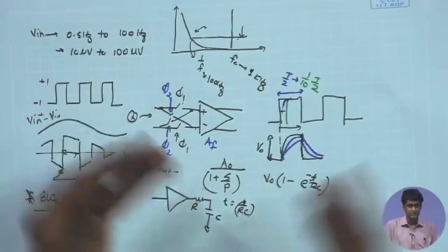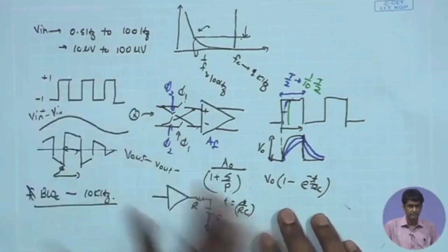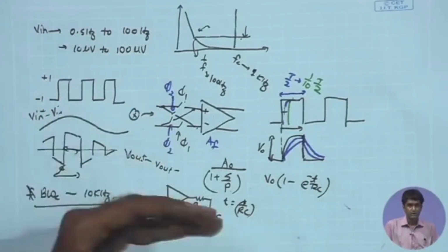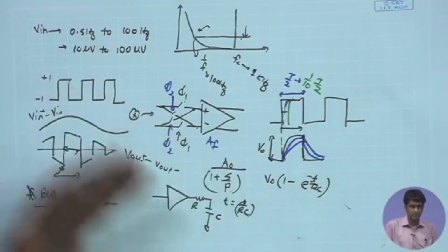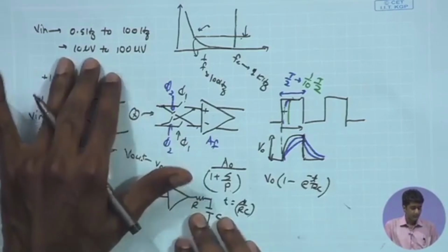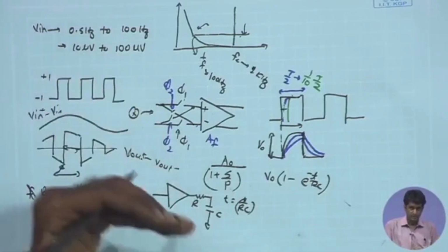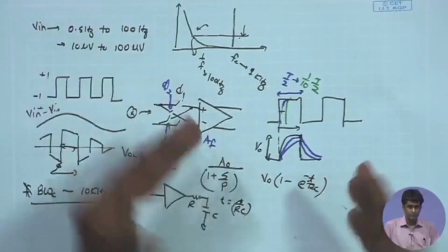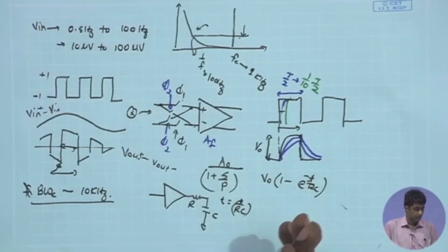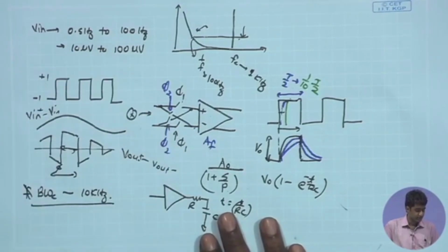Rather than going for single stage, we can divide it into 2 stages, and one single amplifier was supposed to have a closed loop gain of around 50 to 100. So let us take it to be 100 at the max. More reasonable numbers are 30, 40, 50. So let us be more aggressive. Let us take closed loop gain of around 100 for each stage,